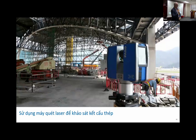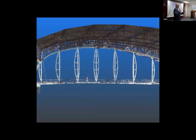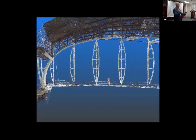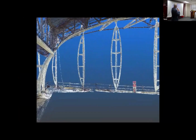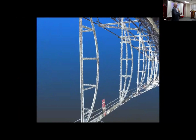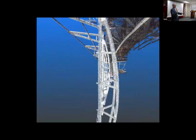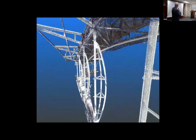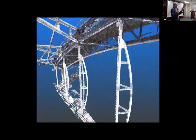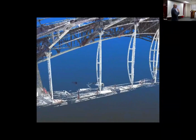So laser scanning basically captures the site condition as millions and millions of points. So you can see here, this is the actual scan of the steelwork. So this is basically a method of surveying the actual project, and then you get a 3D model from the project. And the advantage with this is it's very, very accurate. It's plus or minus 5 millimeters accuracy. So you have a very accurate survey. It's very quick.